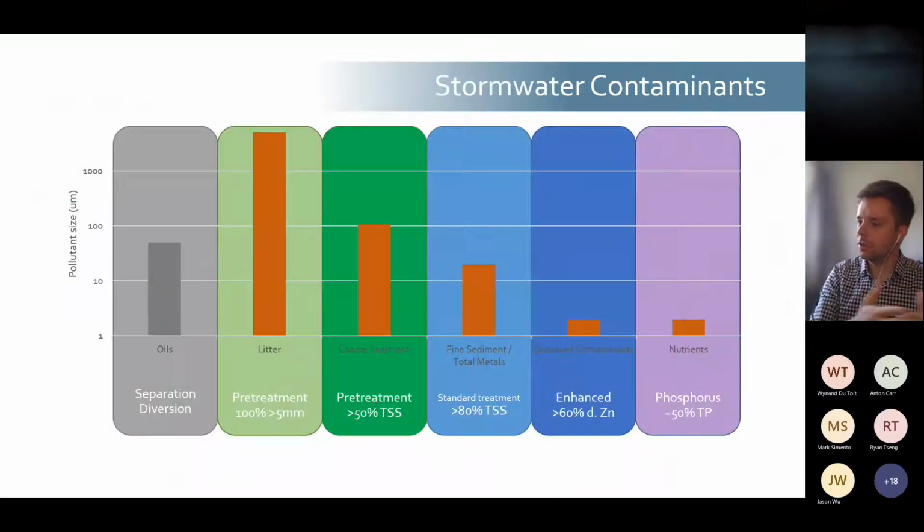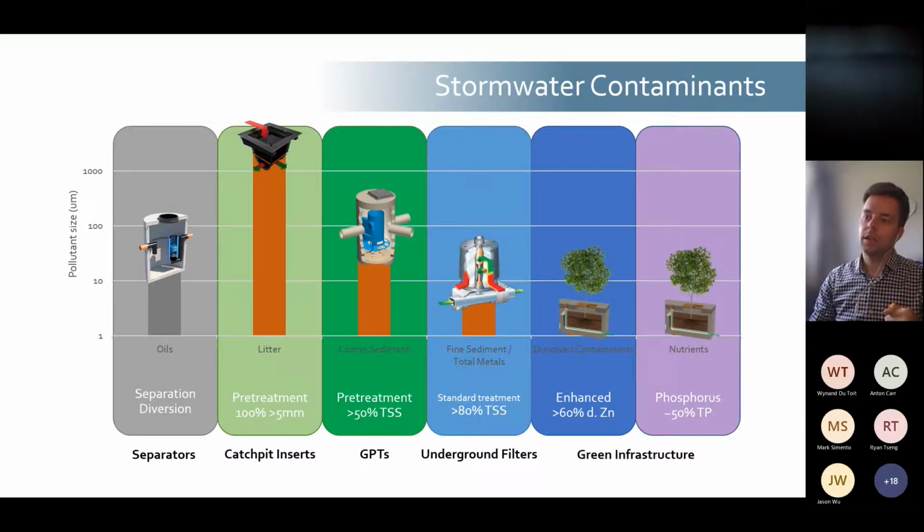Now, if we go back to the different levels of treatment, instead of having a rain garden design or a specific swale design for a certain level of treatment, we have a range of devices. A comprehensive line of widely approved BMPs allows you to identify that we need this level of treatment, so let's put in this type of device. Different sites have different levels of treatment, and some councils consider that as part of an approval process. Some councils will say you have to have an approved underground filter for 75% TSS removal.